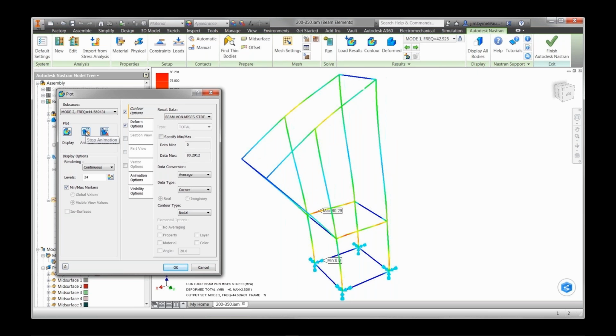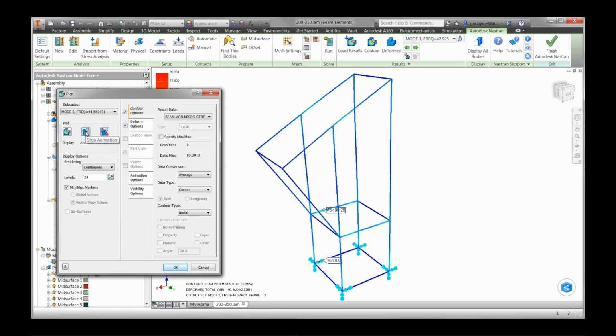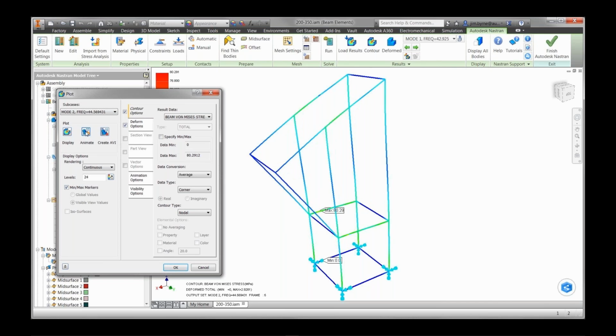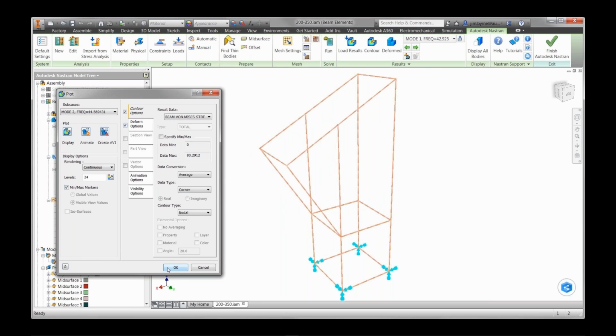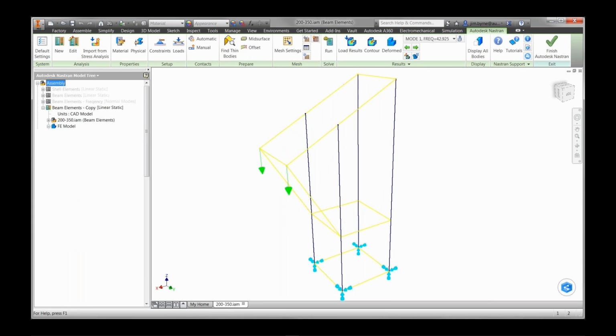It's bending into the front. So this is dangerous actually. If it is bending in the front, it's dangerous. So that's where we have to take a call whether it bends too much, where we don't have a chance to reduce any material, or we do still have a chance if the bending is not too much. That can be found out using the transient analysis. So the next step would be to do a transient analysis on that, and try to find out how the bending occurs when the swing is happening.